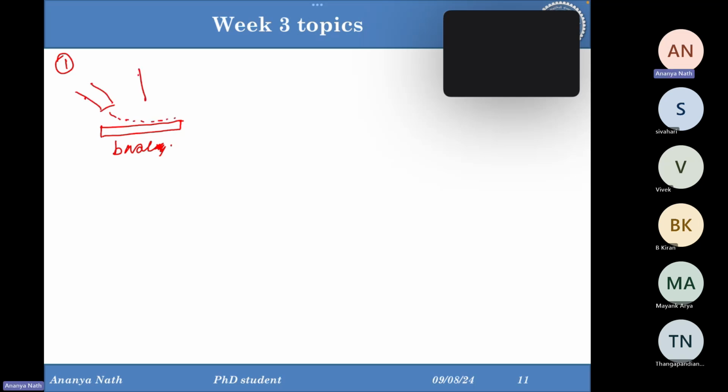From here, the liquid comes. From here, the laser comes, and this liquid head moves in XY direction. So it will just solidify the resin which is spread over the build plate by the exposure of light. Laser is also a light source.